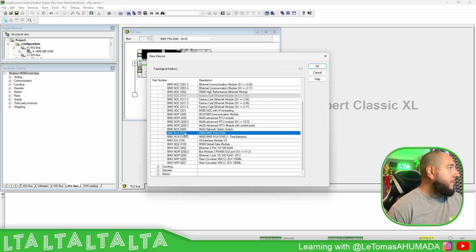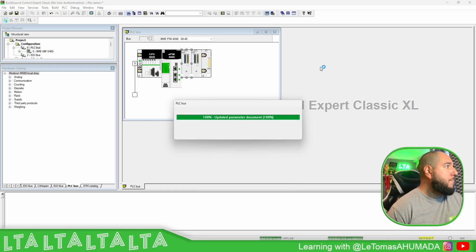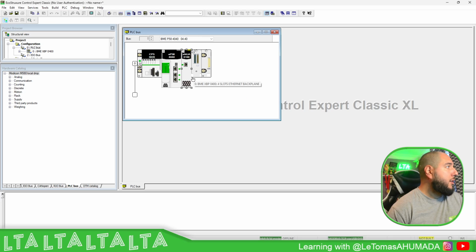This one is the one I have. Here you can see that I have a control port, but I also have the possibility to use the backplane port, which needs to be on the same network as the M580 configuration. The control port side needs to be different.